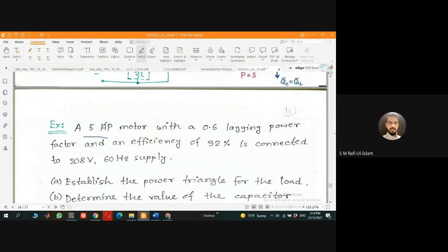If you want to buy a motor, or let's say some tube well, some motors are used nowadays for household or agriculture purposes, and these ratings are given in terms of horsepower. Another thing is also written, the power factor. If power factor is given, then another piece of information will be given, whether this is a lagging or leading power factor. Then efficiency is given, and then the voltage is given as well.